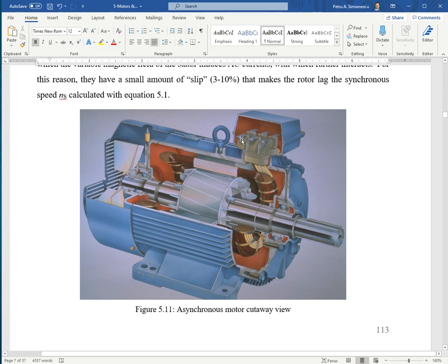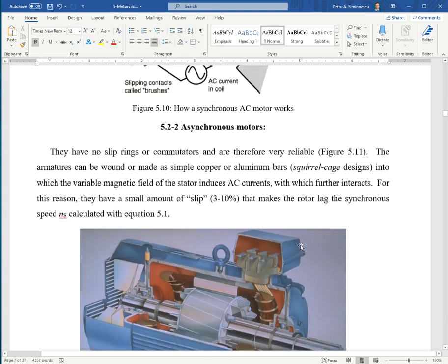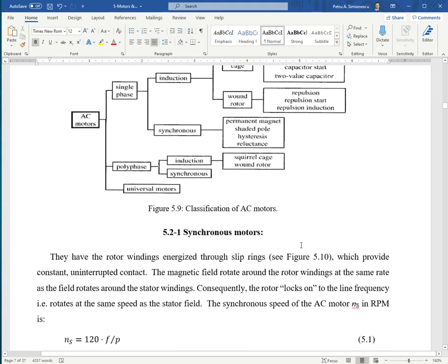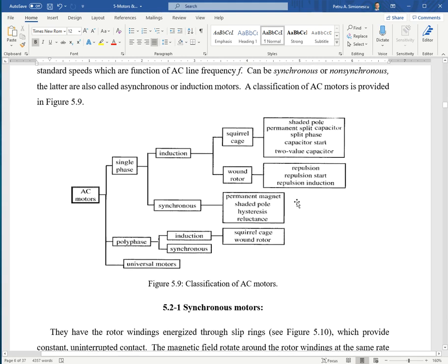Okay, and if you look at the number of contacts, so yeah, this is a 3-phase, but for single phase, you need a means to start them from rest, to break the inertia I said, to reach their operating speed, and it's where you need to supplement. You need the capacitors, and maybe the governor switches.